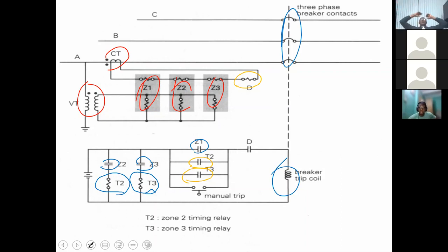One of the things you need to bear in mind is that at your substation, you must have a constant supply of electrical energy, and it is supplied by batteries. So you use a station battery. You don't rely on the utility, except to maintain a charge on the batteries.